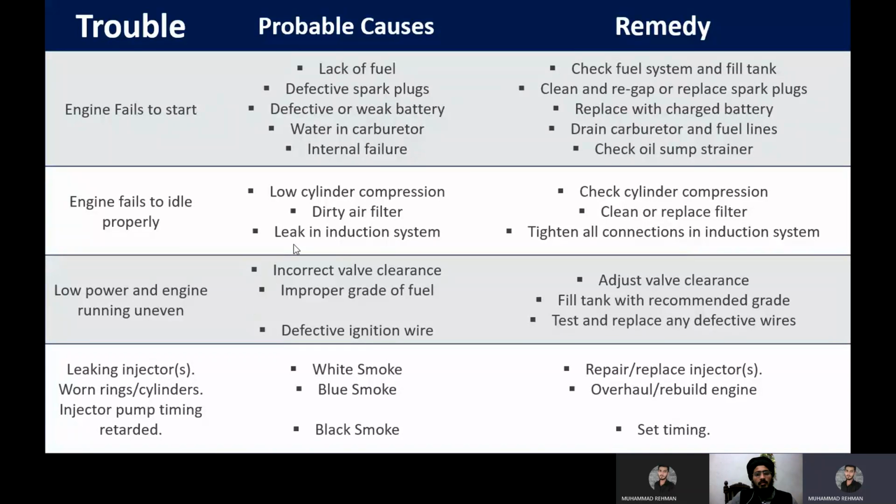If the clearance in the valves is not good, then the valves may get destroyed, or the exhaust and intake occur improperly. The second point is improper grade of oil; the fuel is not up to standard and is not providing the latent heat of combustion, so you are not getting the power.